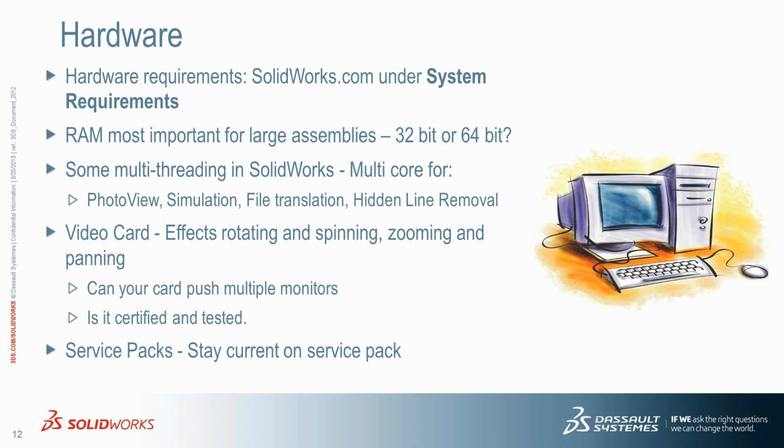When it comes to multiple cores, like my dual quad core, I just wanted to remind everyone that there are some tools in SOLIDWORKS that do support multi-threading, things like PhotoView, the simulation and flow simulation tools, your file translation, and something as simple as converting high-quality views on a drawing or hidden line removal. That will support your multi-core processes, and hopefully in the future we'll get a little bit more of that. So getting a multi-core machine is nice in general because of the speed that you'll gain being able to run multiple things at a time.